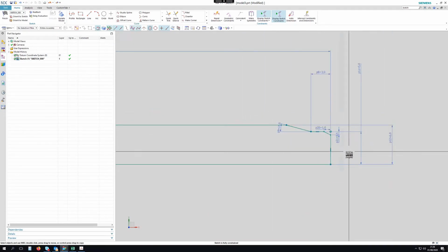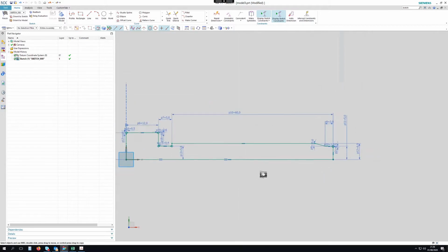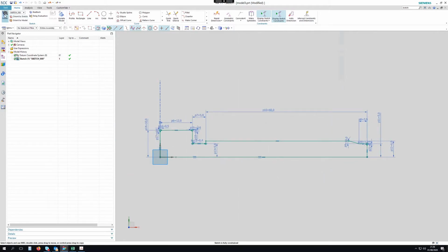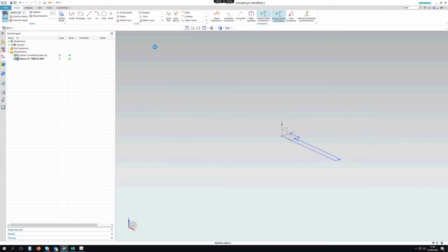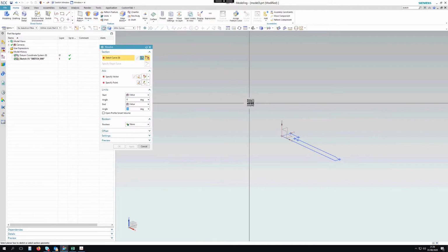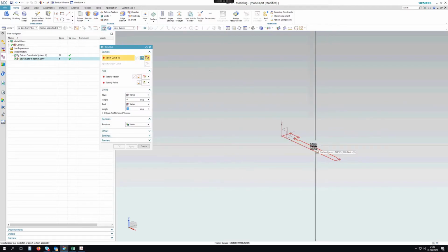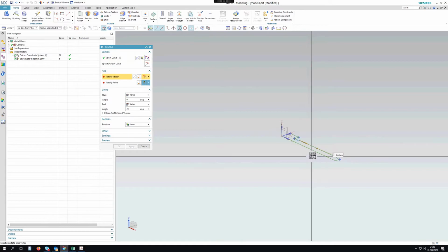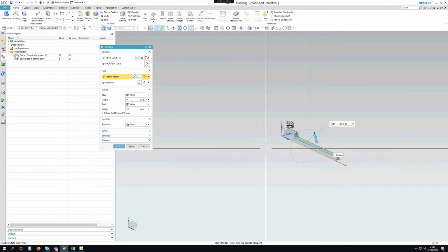Right, so that's pretty much the screw I want. Let's finish the sketch. It's fully constrained. So instead of extrude, I'm going to revolve it. So if I click the little arrow, revolve. If I select the shape, middle click, select the axis.